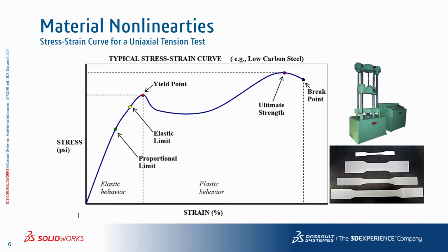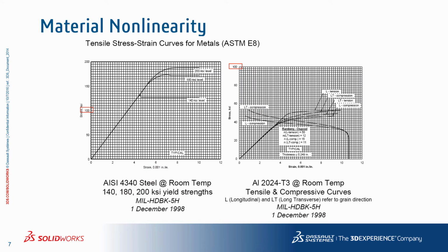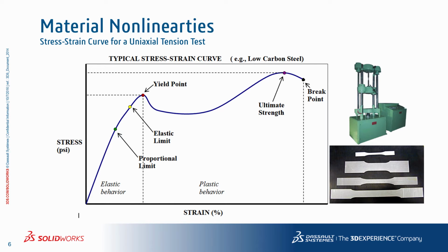Now, stress strain curves for metals are typically measured in tension or compression tests. Typically, a dogbone specimen is used, a certain load is applied, and the response of the strain is measured. That gives one data point on the graph shown here between the stress and strain. Then multiple load cases are tested and the measured response used to obtain the stress strain data as illustrated in this graph.